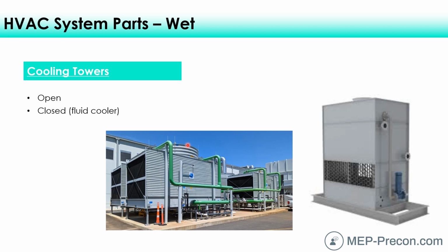And so a realistic consideration for that is perhaps a hotel. If you've got a 10 or 12 story hotel, and you put this cooling tower down on the ground, well, there's certainly the potential in the wintertime, if that operates, which it may, because there might be a lot of interior loads within the hotel that need cooling year-round.